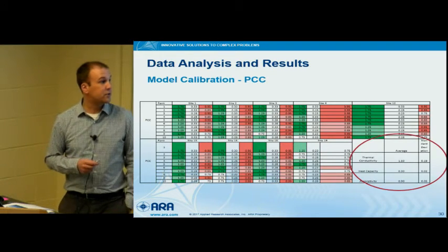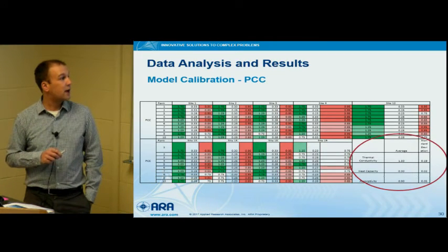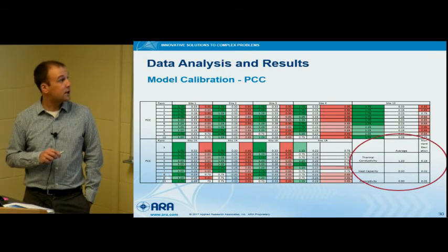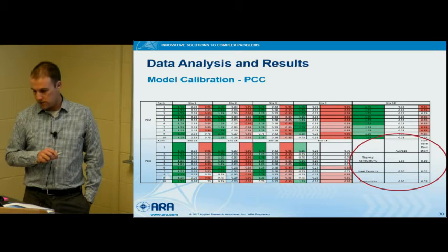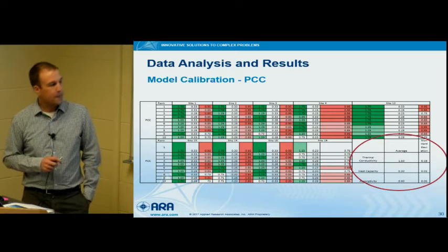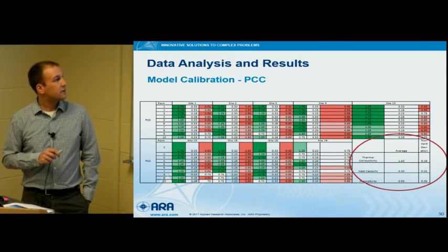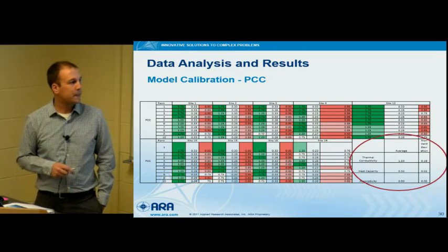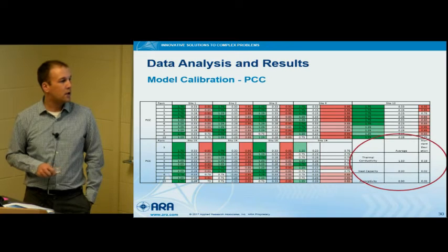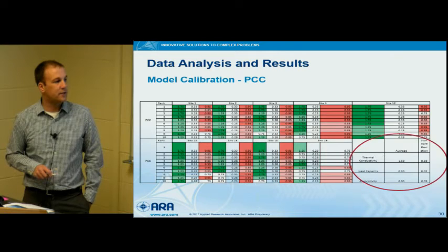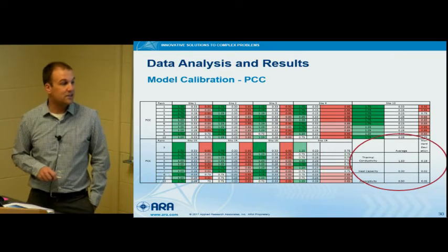So this shows you a matrix of what it looks like. Green is thermal conductivity, white is your heat capacity, and your red is your absorptivity. Basically this one showed the lowest RMSE for site 1, site 2, site 3. Most of these combinations didn't vary significantly, but they did for some areas. So in the end, we came up with an average value. Thermal conductivity is 1.5, heat capacity of 0.3, and absorptivity is 0.9.